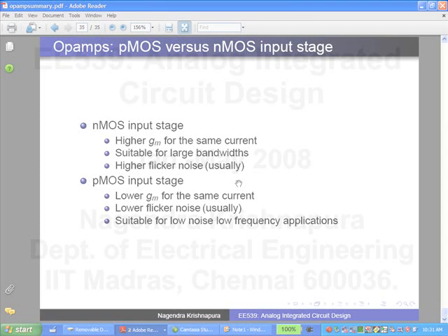Yeah, the question is, if you don't know the load capacitance, how will you use it? Now, there are probably architectures in which that also works, but generally if you have an infinite range for load capacitance, then the only thing that will work is some GM-like stage. If you have a simple differential pair, that will always work. It will become slower and slower as the output load capacitance increases, but it can be stable. Whereas a two-stage op-amp, if you increase the load capacitance beyond a certain point, it will become unstable.